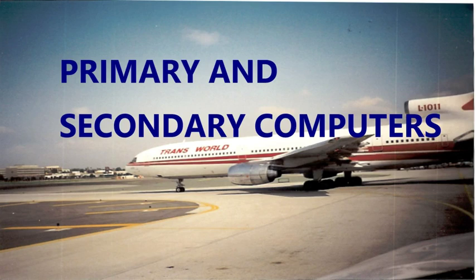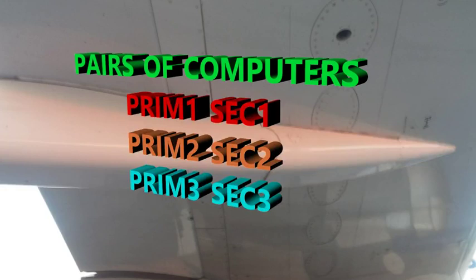So in this particular case, when we talk about computers and the ailerons, or any of these flight control surfaces, along with their actuators, being connected to computers, we're talking about your PRIM, which would be number 1, 2, or 3. And then you also have your SEC computers, which can again be 1, 2, or 3.